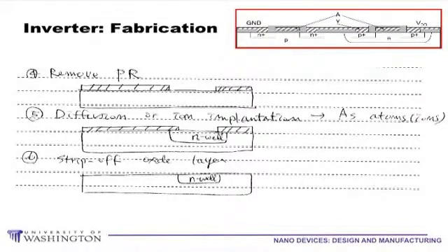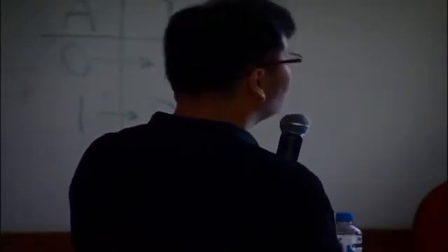Even though it starts from a P-type semiconductor, if we diffuse a lot of N-type materials, then it will become an N well. Okay? So through the diffusion, the N well will be created by using this oxide layer as a mask. And then the oxide layer will be stripped off in hydrofluoric acid, and we go to the next step. So now we have an N well here. That's this N well in the whole structure.